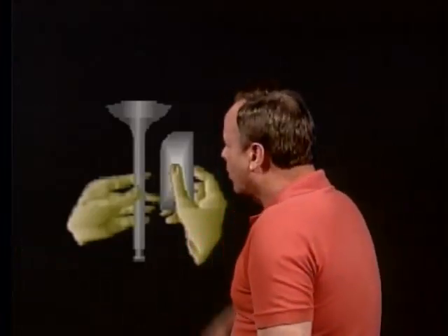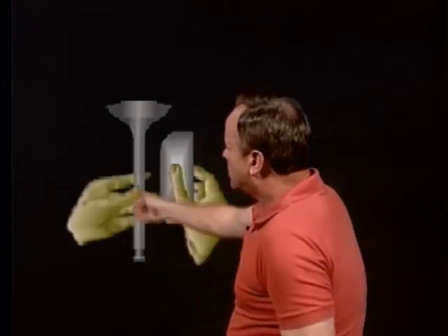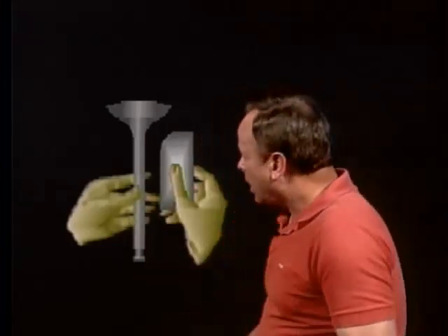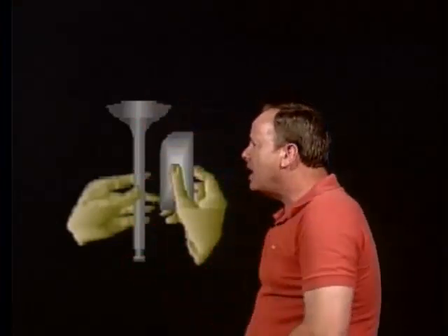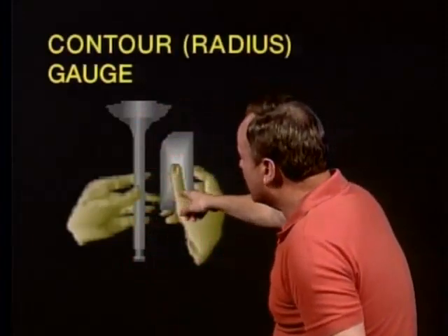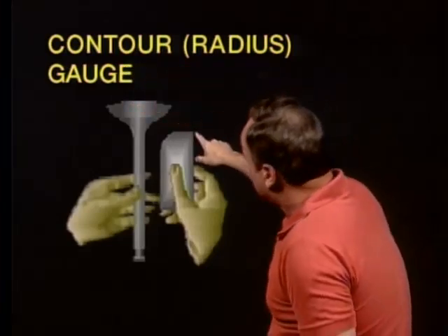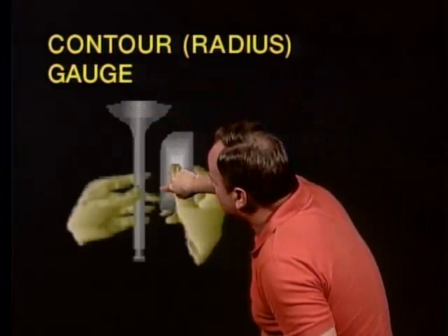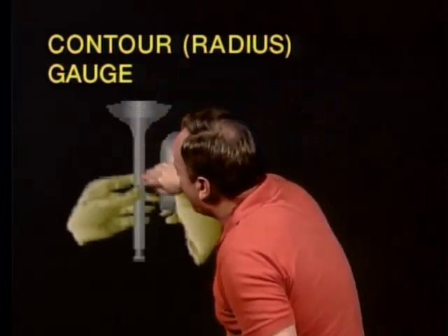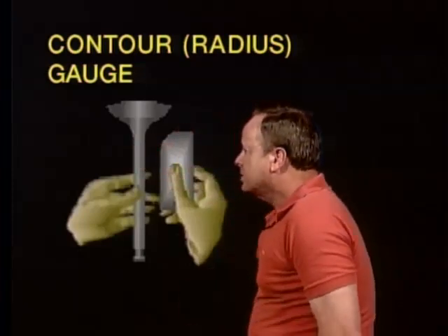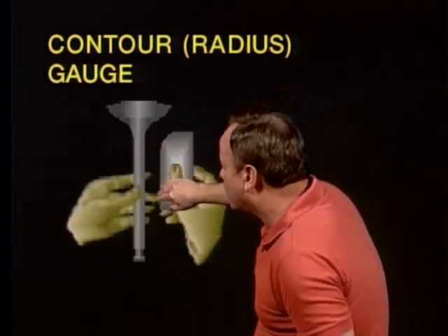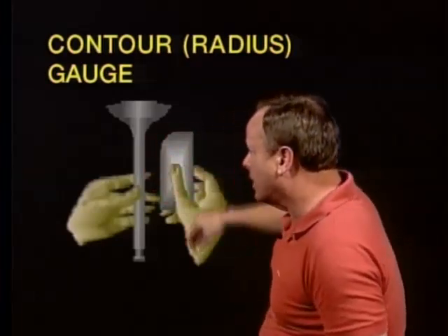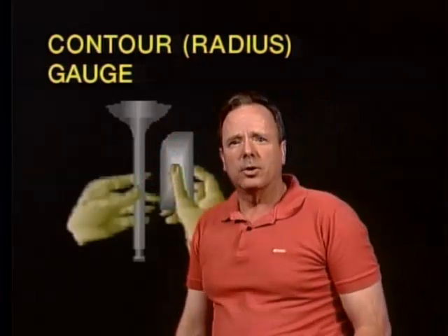So they're going to ask you, let's assume you're overhauling an engine, and you want to check to see if there's problems with this exhaust valve. Well, a couple problems you can have with the exhaust valve is that it can change its shape and it can stretch. Now, how do you measure for this? Well, exhaust valve stretch can be checked by using what is known as a gauge that looks like this, a contour or radius gauge. And it's this gauge right here, and it's matched to the intended shape of the valve, and you see if the valve has its intended shape, and if it does, you're okay. So you'd find out if you had this stretch by visually comparing the curvature between the neck and the head of the valve and this contour gauge. It's generally supplied by the manufacturer. It's also called a radius gauge.